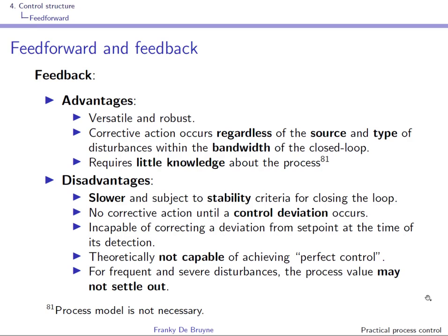Feedback comes with a number of advantages. It is versatile and robust, which means that the feedback principle will work to reject any source of disturbance and any type of disturbance, whether it is a load disturbance or an output disturbance. Of course, as long as the disturbance is within the bandwidth of the closed loop system. If you use a PID type controller, then little knowledge of the process is needed, right? But of course it might help when you're tuning the PID controller.